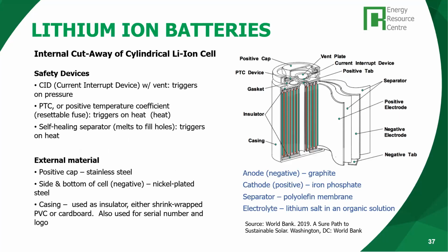Very quickly, what would a cut of a lithium-ion battery look like? The main difference, as I said, is that there is a membrane separator between the cathode and the anode, and the electrolyte, instead of being a mixture of water and acid, is a lithium salt dissolved in an organic solution.